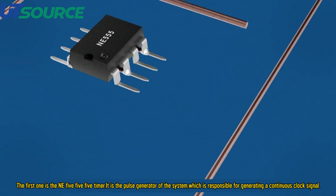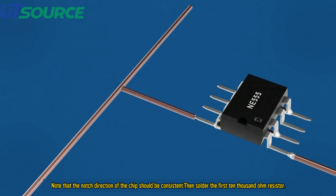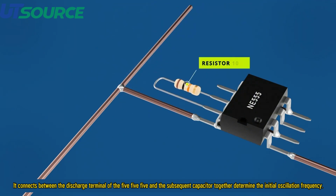Note that the notch direction of the chip should be consistent, then solder the first 10,000 ohm resistor. It connects between the discharge terminal of the 555 and the subsequent capacitor. Together they determine the initial oscillation frequency. Let the LED start to flash at high speed.